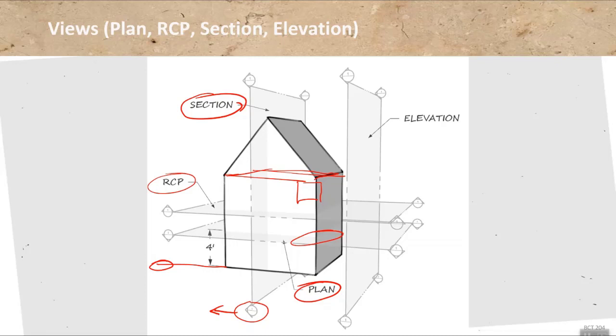Now, if you took that section and you pulled it out and looked at the entire building from the outside, then of course it's a building elevation, and that again looks one particular direction, typically towards the building if you've done everything right. And that of course shows you things like facade details and so on and so forth. There are also interior elevations, which I haven't illustrated here, and you can kind of imagine how that looks. Interior elevations are typically bounded by the ceiling and the floor, so it's not a section, but a portion of a section actually becomes an interior elevation, obviously. Okay, so that's in theory how it looks.